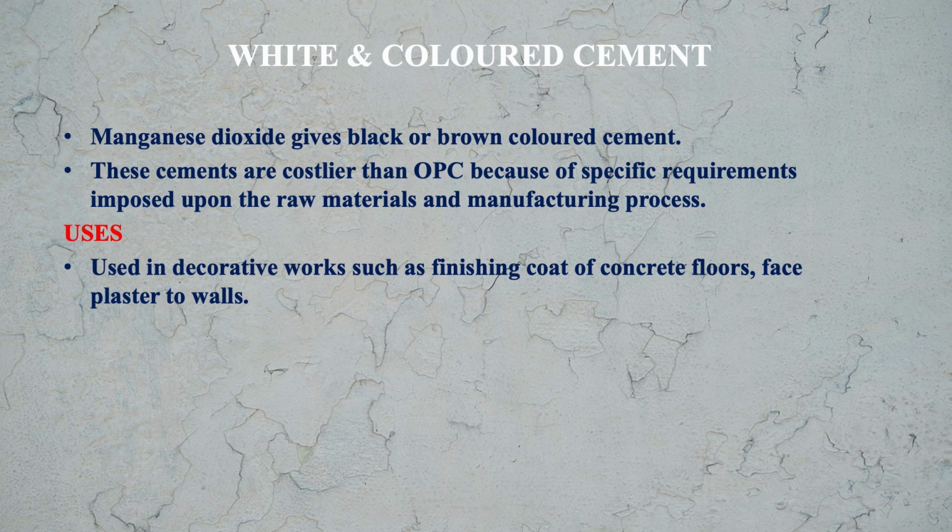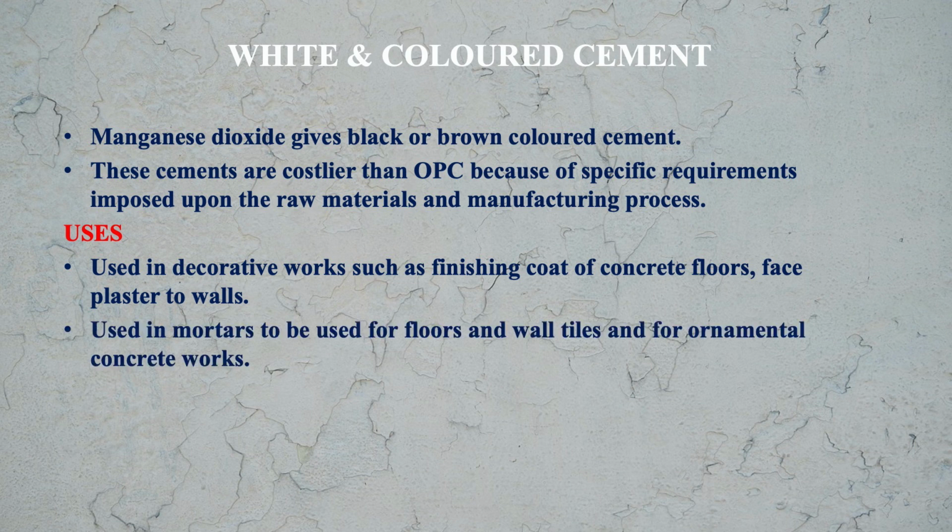Also, these cements are used to make mortar, which will be used for floor and wall tiles and for ornamental concrete works. For decorative and ornamental concrete works, you can use the colored cement and the white cement.